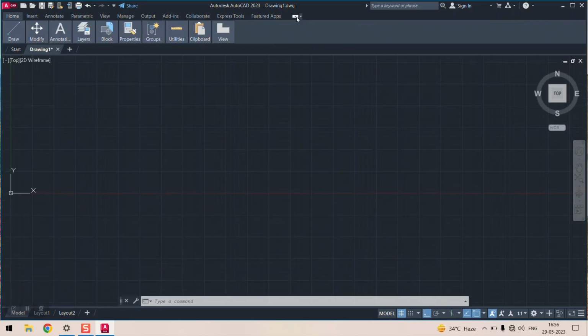If you click on this, see, your ribbon is completely minimized and your panels are available. Commands are completely gone. In order to go to the draw panel, you just click on the draw panel. All the options or all the commands are available, right? Similarly, in modify also all the commands are minimized inside the panel of modify, right? Then if you again click on this, as you can see, your drawing area has been increased from that particular area to this much area.